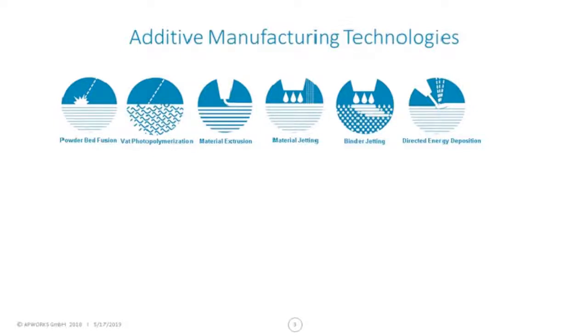The next technology, actually, if you saw it, you would probably think it looked exactly like welding or cladding, if you're familiar with those technologies. Directed energy deposition. Essentially, the difference here is you're providing an energy source which is moving around, normally a laser beam or an electron beam, which is creating a molten puddle of material. And then you're pushing into that molten puddle either a wire, as you would with a classic welding process, so stick welding, or you're spraying a powder into that melt pool. And by moving that energy source and that material around, you're able to selectively build up a part.